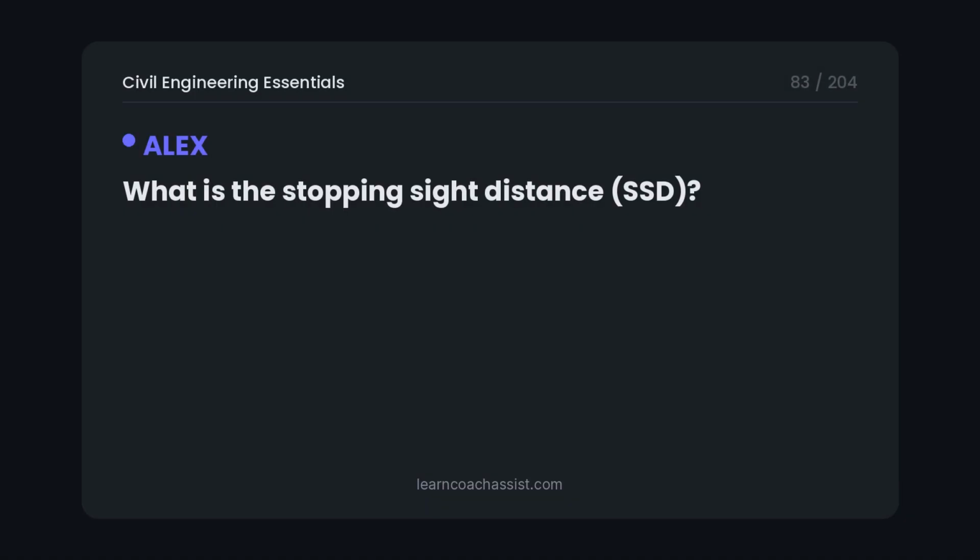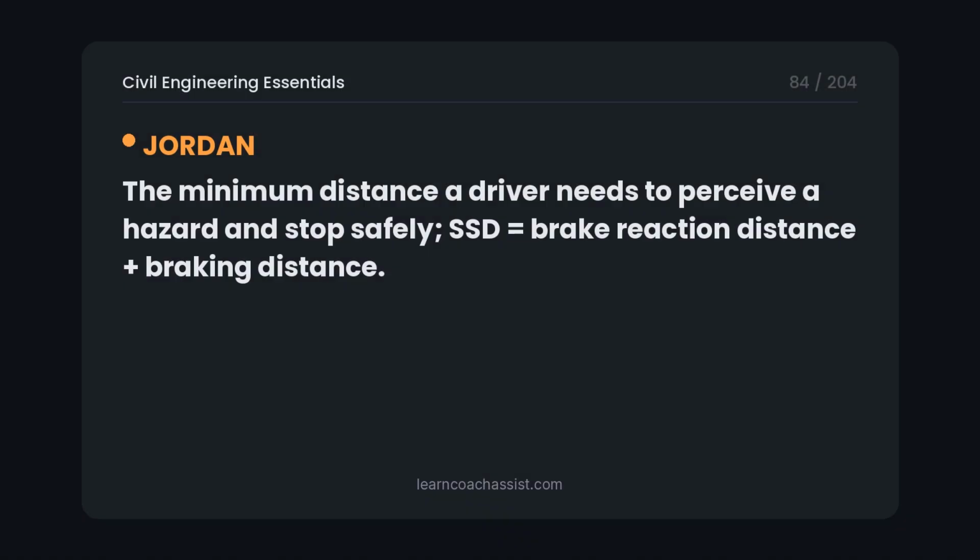What is the stopping sight distance (SSD)? The minimum distance a driver needs to perceive a hazard and stop safely. SSD equals brake reaction distance plus braking distance.